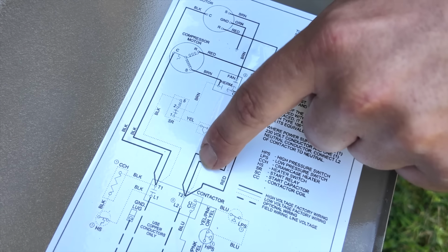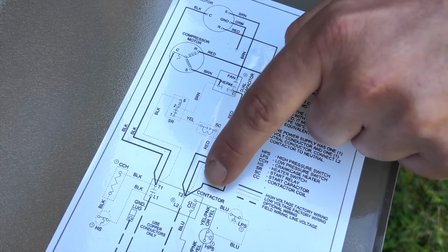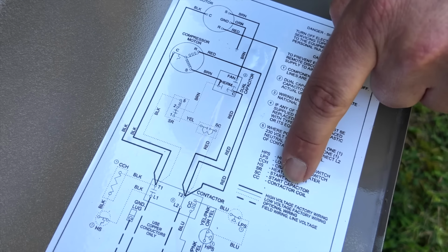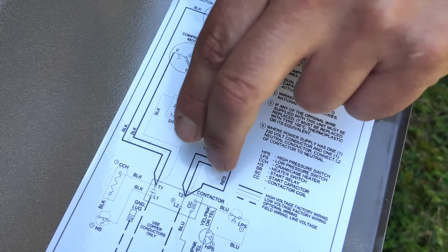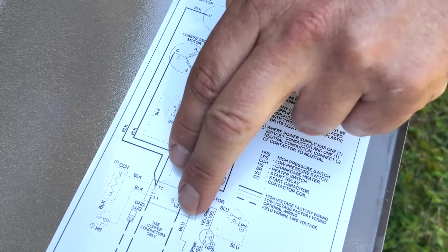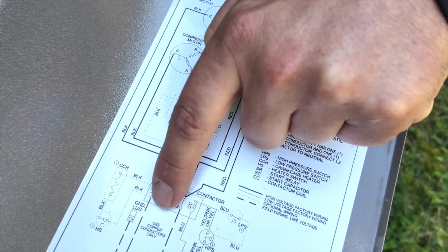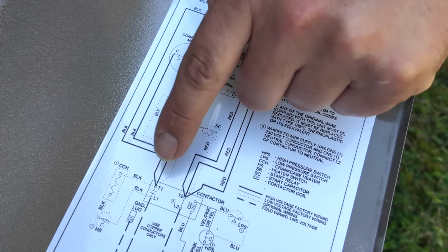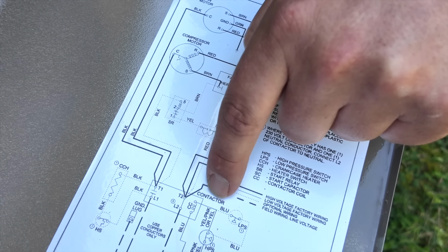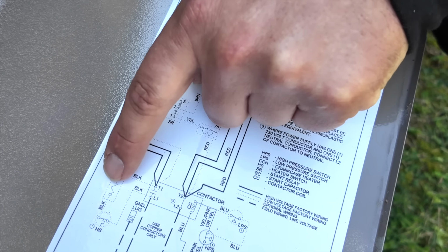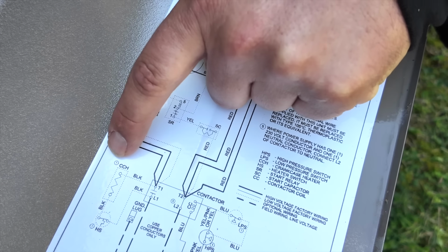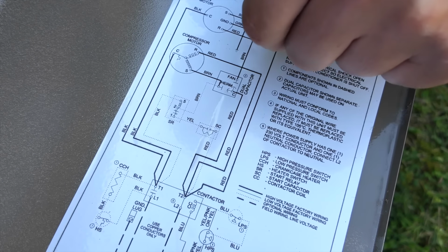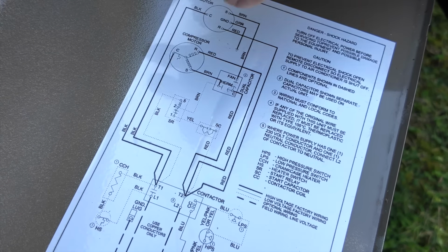And here's the contactor. How do we know it's the contactor? It says right here, contactor. And then we have the CC. Remember on the legend, it says contactor coil. And then you can see that we've got our L1 and L2 being fed by the power supply coming into the unit, single phase, 208, 230. And then we've got our coil, blue, yellow. We've also got some optional things over here. When it's got a 1, a number beside it, usually that's a note. And you'll come over here and you'll look at the notes. This is how you read a schematic for an air conditioner.